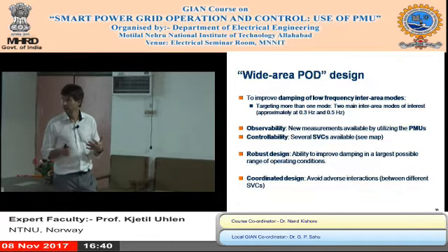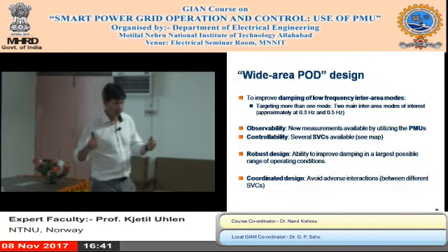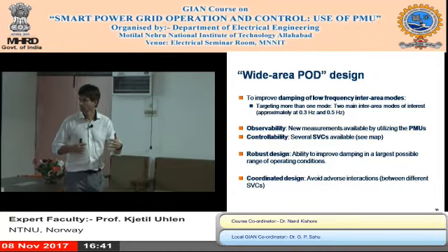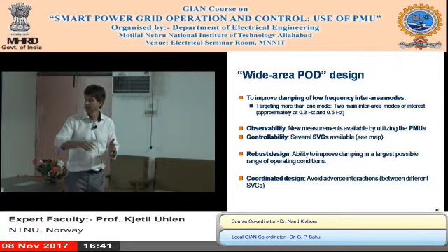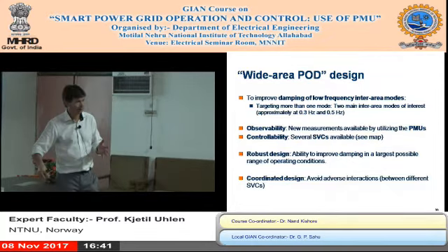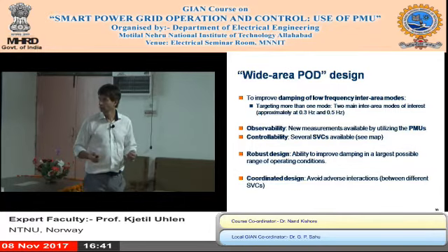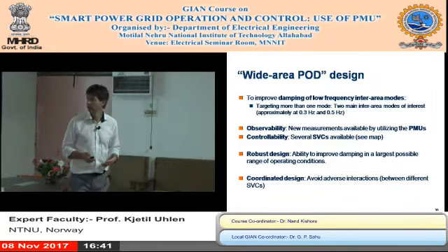Then you could utilize wide area measurements in order to get better observability of the critical mode. So instead of filtering your local signal, you select signals which have good information about the mode in question. You could also do something about the controllability by operating conditions, possibly involving more than one mode. And we do want to do a coordinated design to avoid adverse interactions.